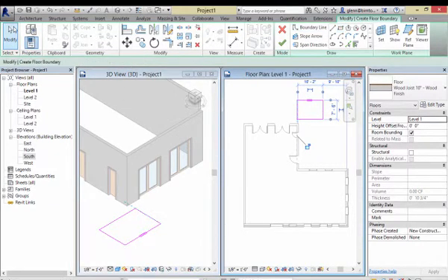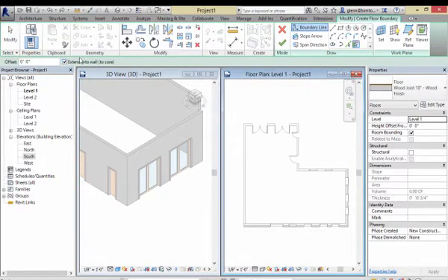Instead, what I'm going to do is use the pick wall tool. Pick wall actually does have a little bit of nuance to it. When I pick the walls, should I draw that to the core of the wall or draw it to the outside or inside face of the wall? The truth is, when it's choosing by default, core is usually the better choice, because the way we tend to build things, we'll have a floor, we'll have the studs line right up to it.